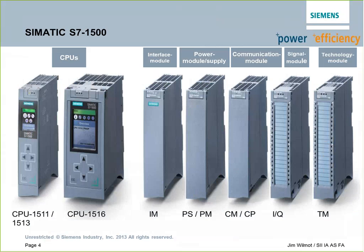It actually is similar to the 300 system. Those of you familiar with that know it's a modular design. So we have CPUs and I/O modules, and they fit on a DIN rail and create their own backplane as we go. There are little U-shaped connectors that fit behind the modules and interconnect as we go out on the DIN rail and create a bus. This is a little bit different than the rack-based PLCs that you've seen, where you buy an 8-slot rack or a 16-slot rack and then fill it up with I/O cards. This way we just make it as we go, and the 1500 allows us to go all the way up to 32 modules on the local rack.